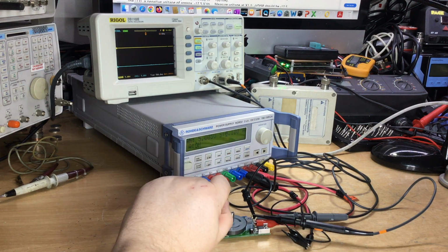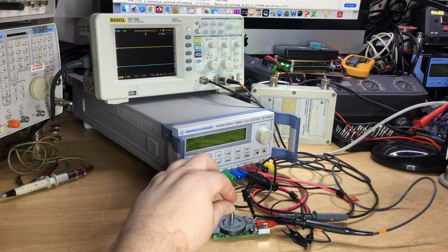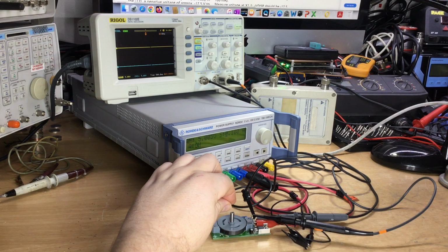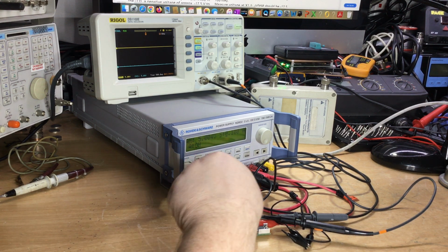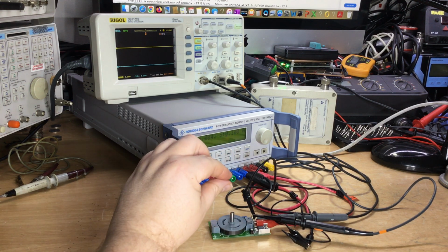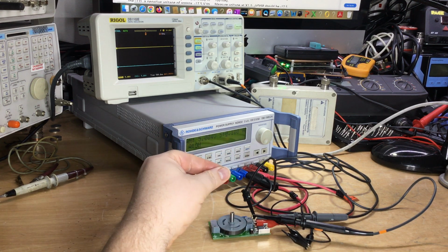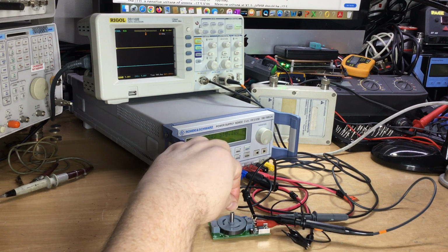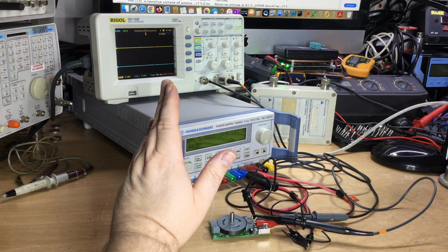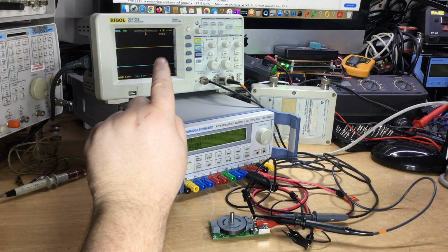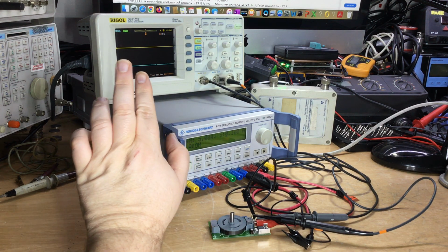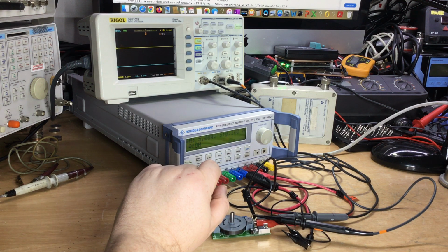I slowed the time base right down so that what I'll do is I'll turn this control and I'll count out 1, 2, 3, 4, 5, 6, and each time I call out a number I'll do an indent within the control, so it's a couple of hertz in frequency. So because I've slowed the time base down, we're able to see the signature of both sensors at the same time and compare them.